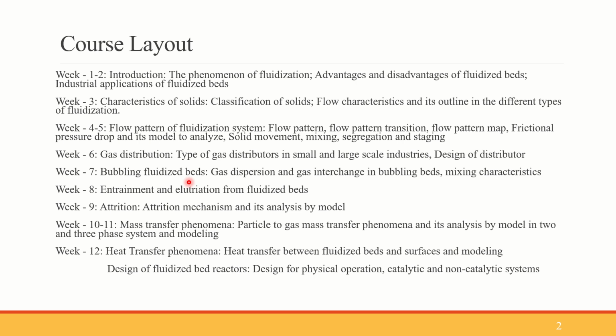We see the flow pattern from the packed bed condition, then the minimum fluidization condition, and later, if it is a liquid fluidized bed, homogeneous fluidization. If it is a gas-solid fluidized bed, we will have the presence of bubbles in the fluidized bed.